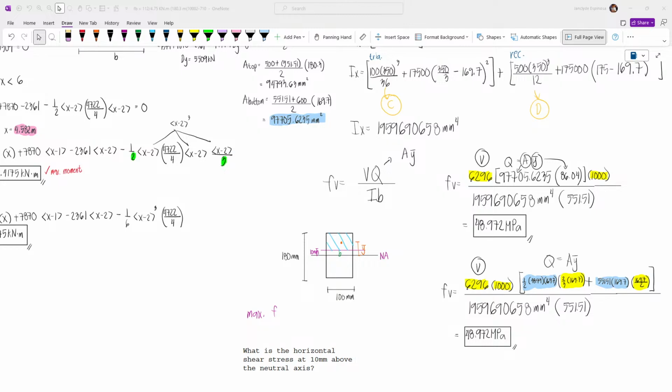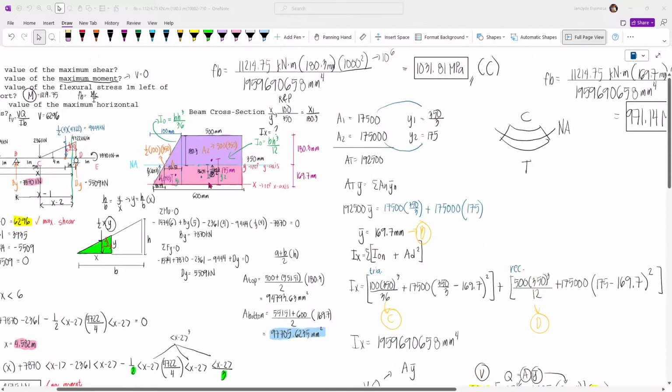In the board exam, rectangular sections are the most common. Sometimes you get irregular shapes, or shapes with a geometric center like an I-beam or a hollow circle. In your example, this is difficult because it is trapezoidal and irregular. You have to solve the centroid and the moment of inertia.